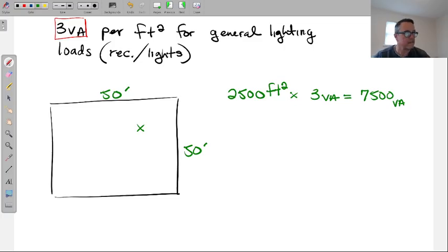So the next step here is Ohm's law, because this is what we've done. The first, we've described wattage. So from here we do Ohm's law, 7,500 VA, and now we're going to divide it by a voltage. Now, this is why 210.6 was before this one, because 210.6 gave us the voltage that this has to be.